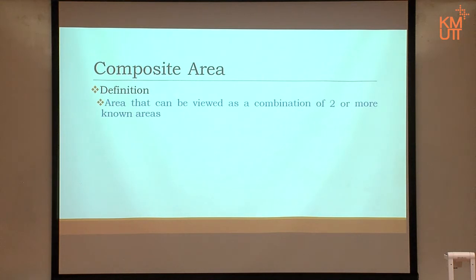In that case, the way we analyze it, we will actually define all components first, then use the parallel axis theorem to find the small areas' moment of inertia depending on which axis. Then we know it through its own centroid, then we can move the axis to the common axis, right?